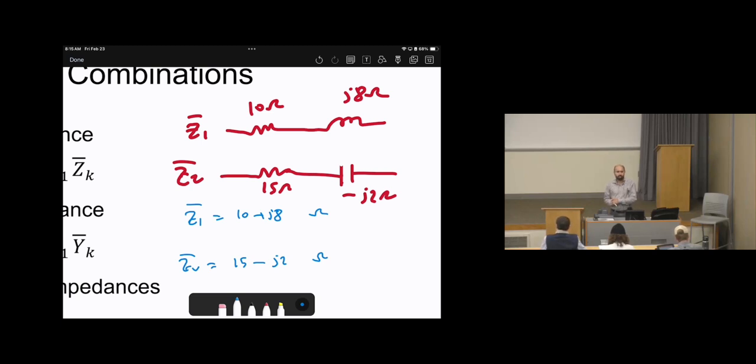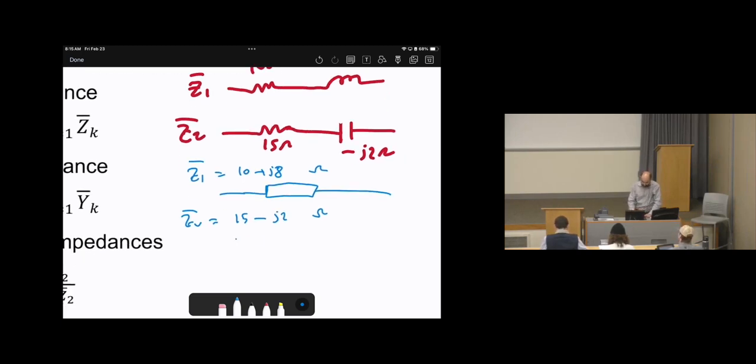Now it's a complex number, so we cannot put a resistor. We cannot put an inductor. So what should I put as the symbol? Put a box. Whenever we have a complex number, you can put it as a box. This is a box for Z1. This is a box for Z2. Okay, so we can avoid the confusion. In the equivalent circuit, just put a box.